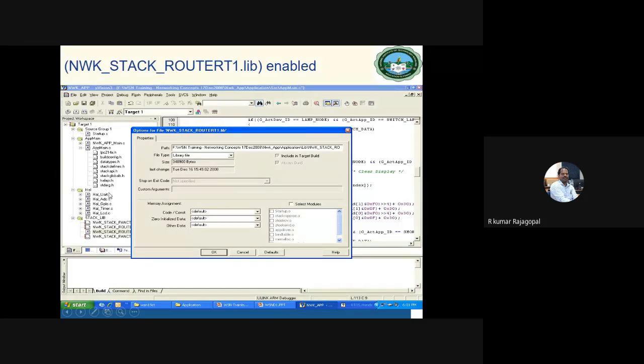If you want additional .c files like UART.c, ADC.c, GPIO.c, timer.c, LCD or maybe other .c files, you can take them as a HAL, hardware abstraction layer. Nothing but you can take them as separate C files also. Totally you can integrate the header file into the main file, and other header files can be separate. You can add a header file for the particular process. Whatever additional devices you have, you can add as a separate file.